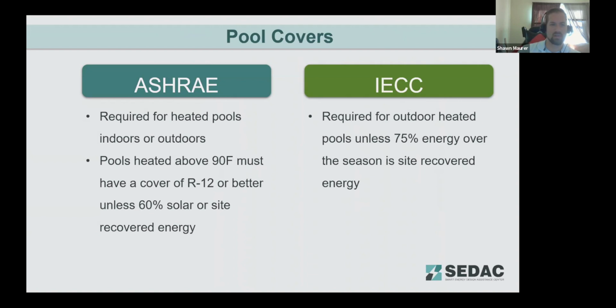For pool covers, what we see here is a substantial difference between ASHRAE and the IECC. ASHRAE requires pool covers for both indoor and outdoor pools, whereas the IECC only requires it for outdoor heated pools. For warmer pools, such as therapy pools, the cover must have an increased insulation value, that R12 that's noted there. So the main thing we're looking at here, again, you're predominantly reducing evaporation from those pools, which increases that heating load and also increases chemical replacement costs as well.